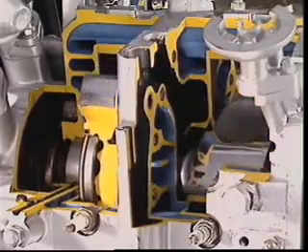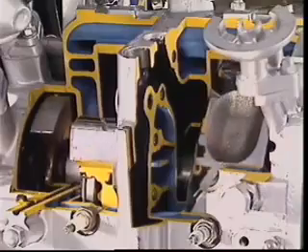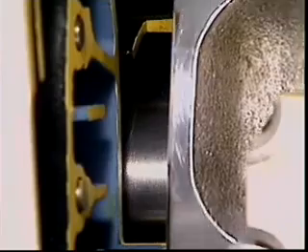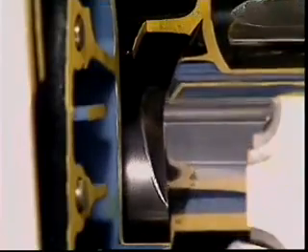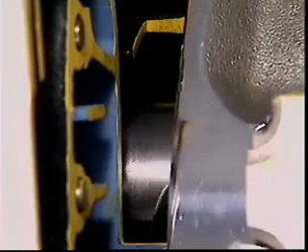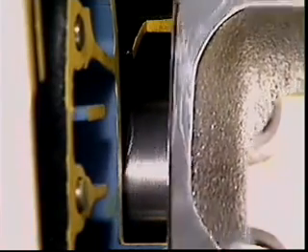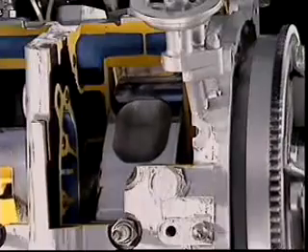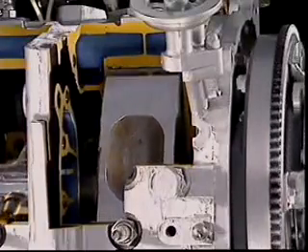What if 2 rotors are bolted together? Then their output is similar to that of a twin-cylinder 2-stroke engine. Because of the ratio of the gears in the housings and rotor, the eccentric shaft makes 1 revolution for each power phase. That's the same as 3 revolutions for each rotation of the rotor. So the eccentric shaft turns at 3 times the speed of the rotor.